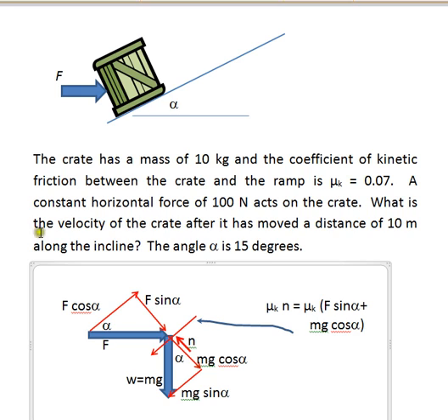Okay, well, a key to the problem is decoding the forces and the angles through which they act, and then decomposing them into their components. So just understanding the trigonometry, it becomes important that if the angle alpha is between the horizontal and the incline, that's shown here, then it's also the same angle acting between the normal to the incline and the vertical. So the angle alpha is from the horizontal this way, but also from the vertical this way.